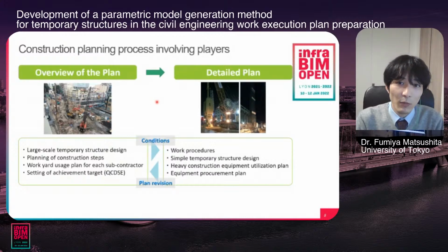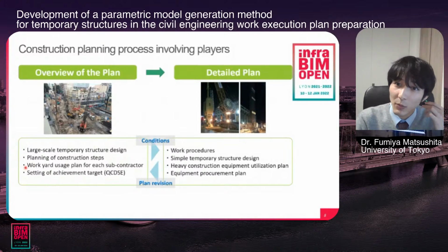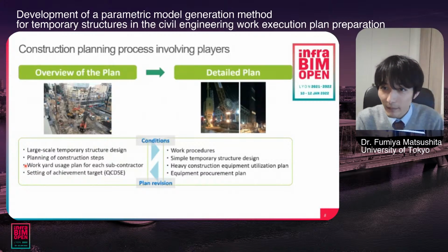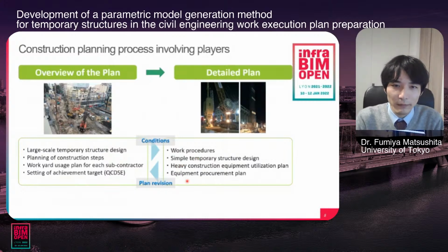The overview of the plan is planned for the following: a large-scale temporary structure design, planning of construction procedures, a work-yard usage plan for each subcontractor, and setting achievement targets. These results of study can be also the condition of the detailed plan. In the detailed plan, based on the overview of the plan, decide work procedure, simple temporary design, and efficient procurement plan.